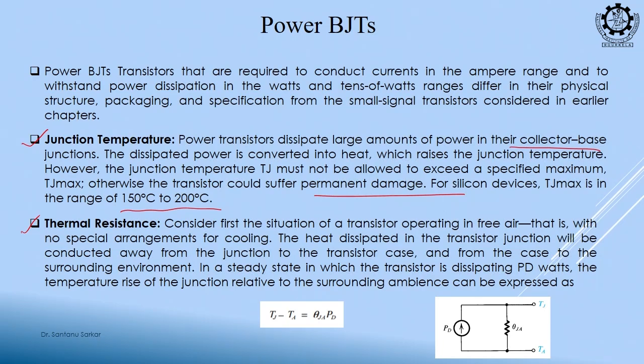So, this thermal resistance is modeled like this: suppose this transistor is dissipating PD watts of power, and the temperature rises. We model that this thermal resistance times the power is equal to the temperature difference.